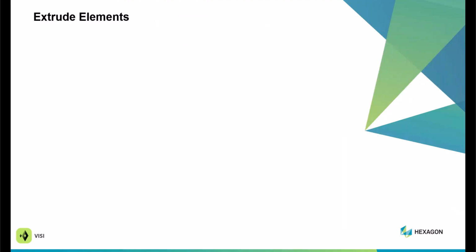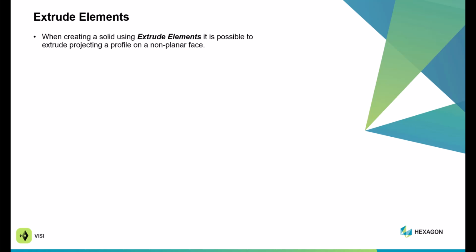So now we're going to get into what's new with extrude elements. When you're creating a solid using extrude elements, it is possible to project a profile on a non-planar face. Non-planar profiles can be extruded as a solid, which previously was not possible.